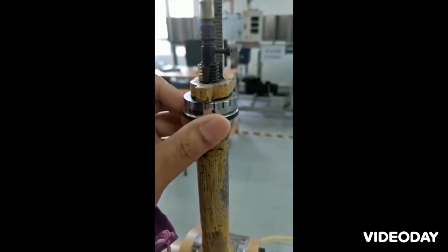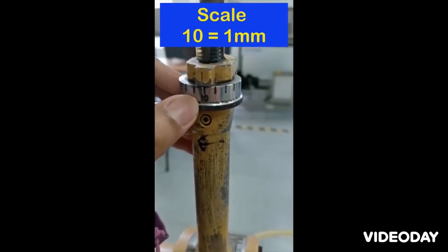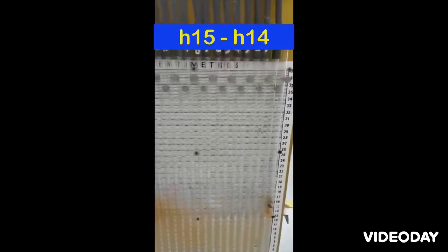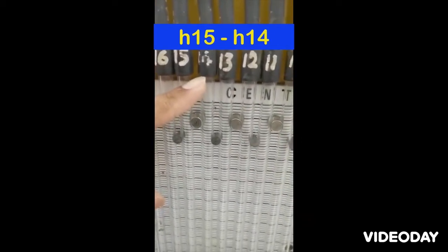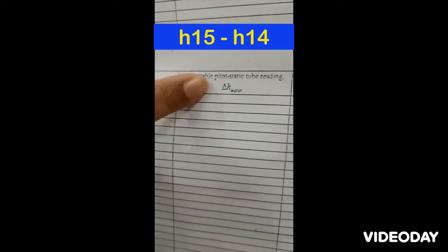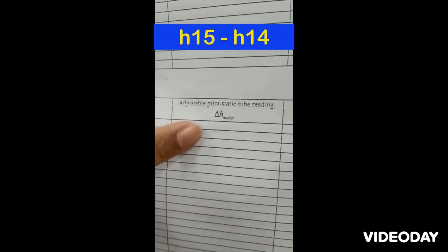Just rotate this pitot static tube until 10. 10 here is equal to 1 mm. So you need to write down here 1 mm. After you set the pitot static tube at 1 mm, you need to get the reading for H15 minus H14. That one you fill in at the adjustable pitot static tube reading, H water.